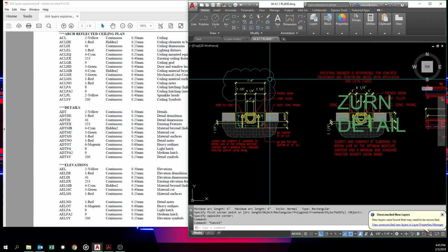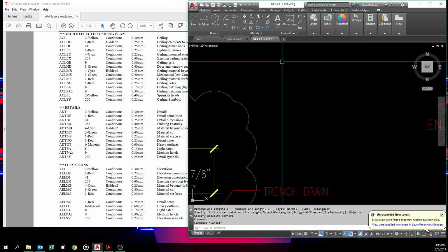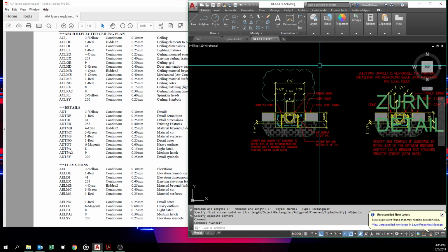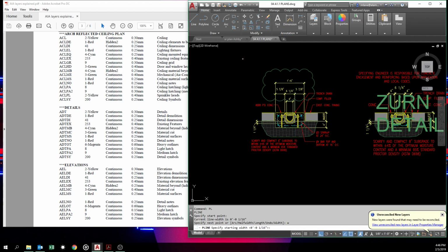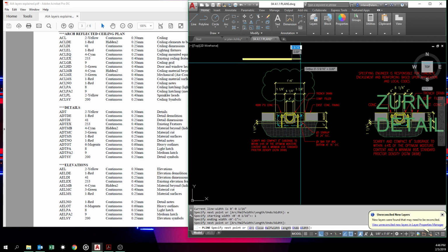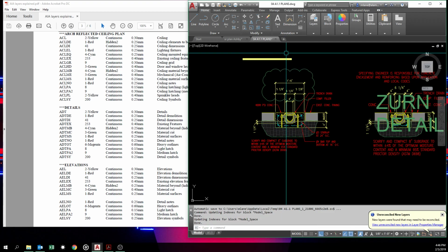And remember I was telling you we can actually assign pen weight to these rev clouds. This is true of line types too, or even polylines. Remember, polyline, we could assign a width to it. So we get width, and we'll tell it 1 and 1. And so now it's fat, right? Let's say we mess it up and we want it to be 1/2 inch.